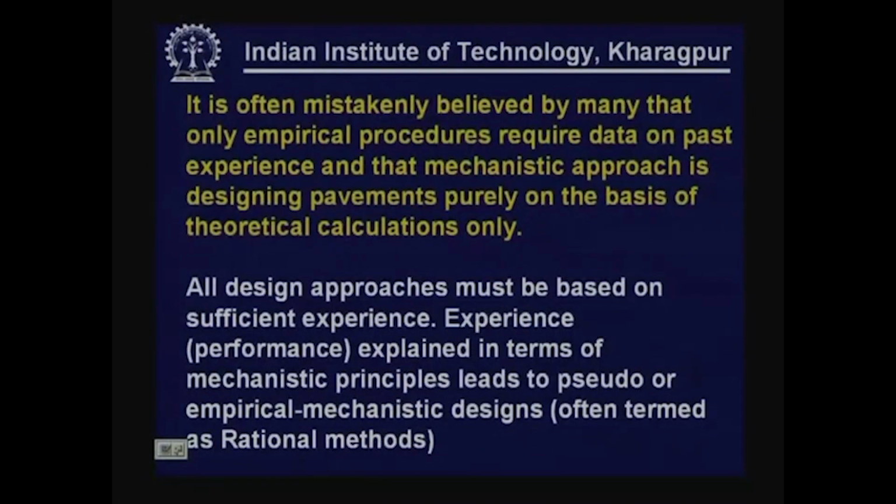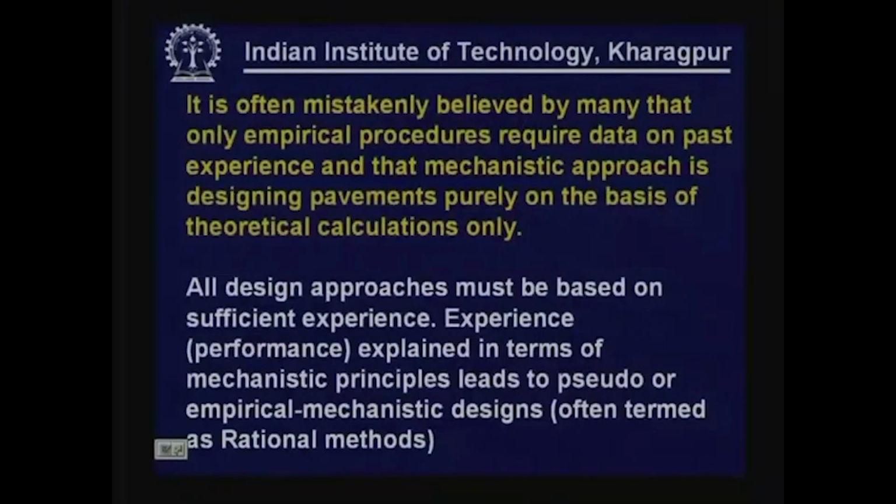It is often mistakenly believed by many that only empirical procedures require data on past experience, and that the mechanistic approach is designing pavements purely on some theoretical calculations, and then using some calculator or computer we are trying to design pavements. People often try to say, when you say I am going to use elastic theory, this theory, that theory, they say this is all purely theoretical, there is nothing correlated to practice. It is a mistake. Any design procedure has to be on the basis of observed performance. By mechanistic approach, we are only trying to explain the performance in a more rational and more fundamental manner.